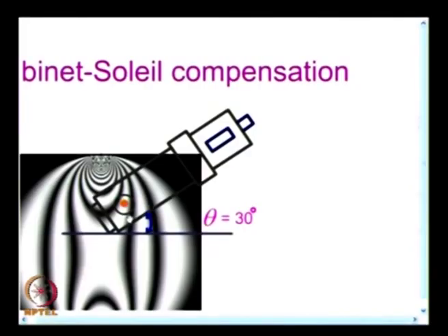The reference axis turns out to be the principal stress direction at the point of interest, and the principal stress direction has been determined from the isoclinic angle. So, now I align the compensator with that angle, then whatever compensation I do, it is possible for you to obtain a calibration between the counter reading and the compensation added or subtracted. It is as simple as that. And what I have shown here is the compensator is put, and this is the field of view.